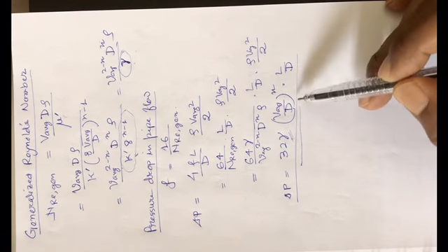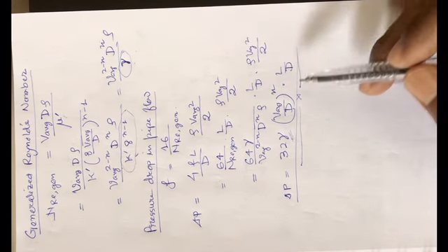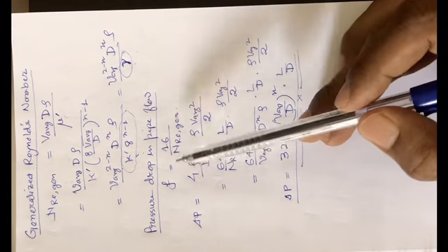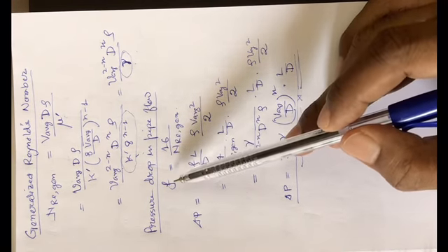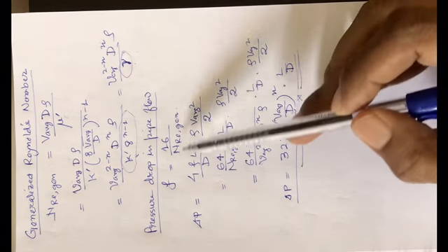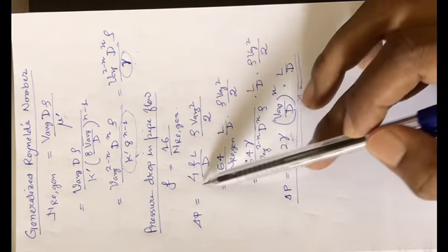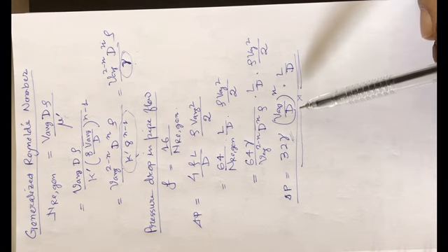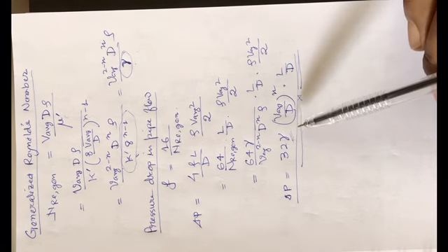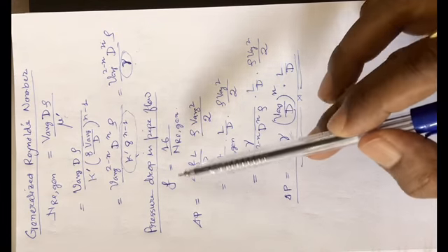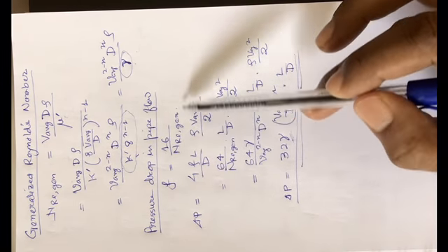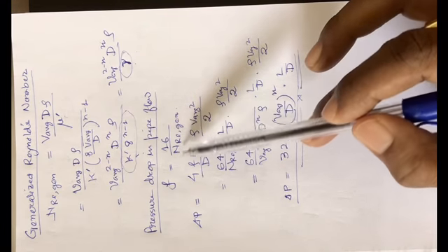So for calculation of pressure drop in the case of a non-Newtonian fluid, we can approach in this way. If we can estimate F here, then we can directly substitute it in this particular equation. We can avoid this complex expression involving some new variables. So you just estimate F by this equation. However, you will have to note that you are taking the generalized Reynolds number.